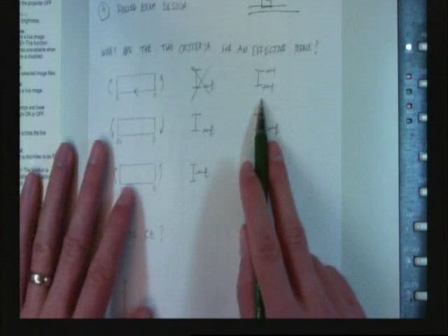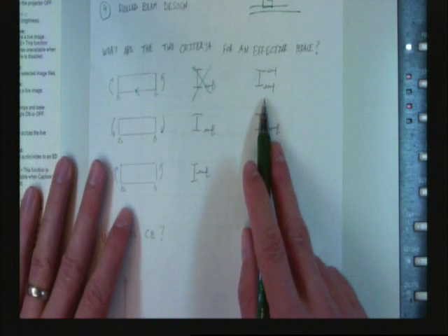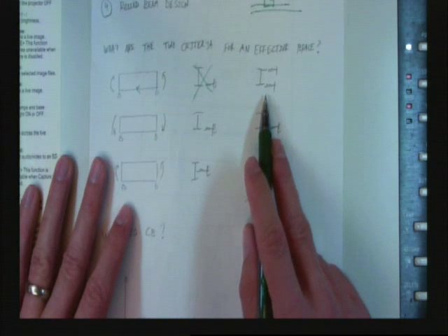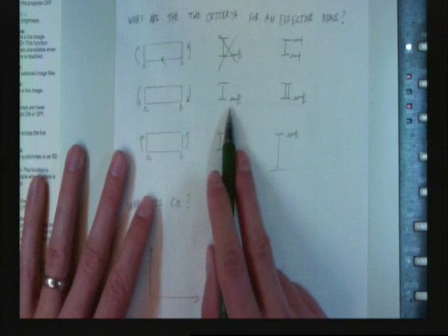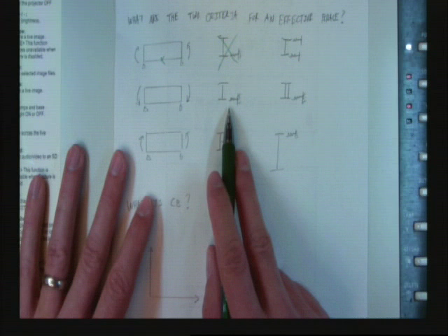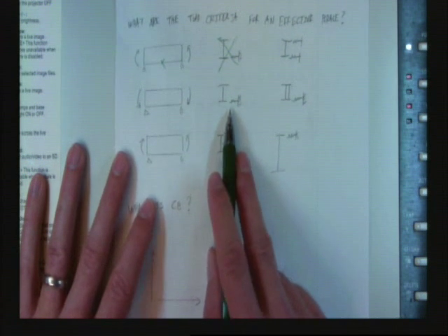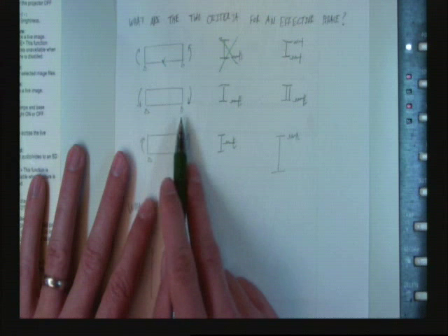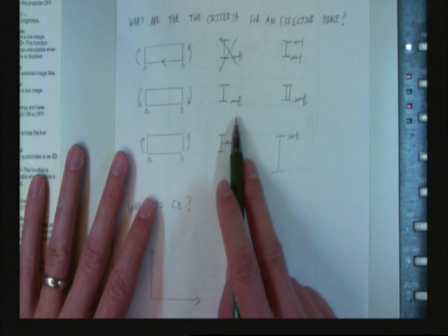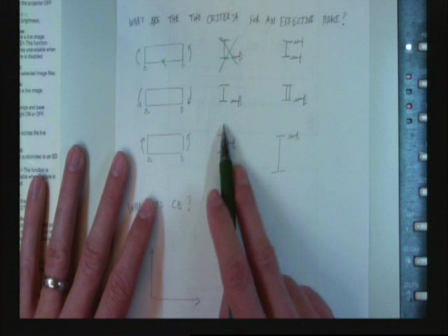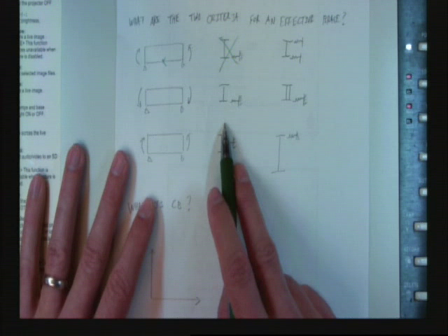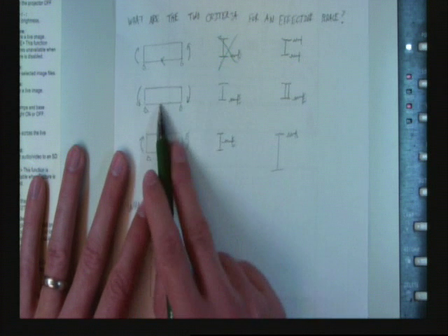How about this one? How come? Okay. How about that one? Okay, so now I'm loading in the opposite direction. So now I have a brace at the bottom. And the answer given was, as long as this is a shallow beam, we're good. That's right. As long as it's a shallow beam, it's good. He said, what? But you're bracing the bottom flange. Yeah, but it's the compression flange now, isn't it?